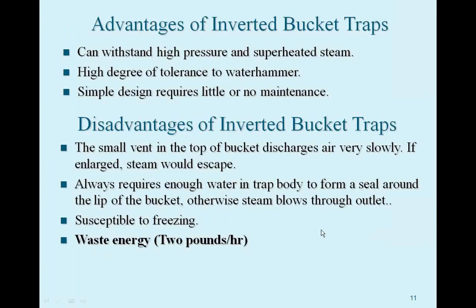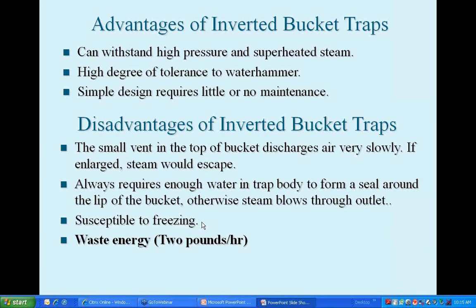There are two problems with that, though. One, you've got to remember to set the prime, as it's called. So if you get a new trap, you've got to prime it. And then the other problem, which is the bullet point here, is they're susceptible to freezing. If you have these outside and they're on an application that you shut down at times, for whatever reason, production shuts down, normal shutdown, planned outage, whatever it might be, that prime in there can freeze. And then that can crack the trap depending on the material that it's made out of, or over time it could even evaporate out of the system, and then you're stuck with a trap that doesn't work when you restart it.